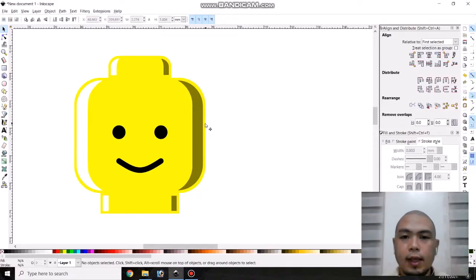Alright. So, yung kanina, when we started working, nung nag-draw tayo, sinabi ko early on na wala mo ng stroke yung shape, kasi yung stroke gives you a certain thickness or outline outside the shape. And it affects the dimension of the shape as you are working with it. So, very important kasi yung mga dimensions na yan, lalo na if, halimbawa, you are designing something for a laser cutting project, na importante yung tolerances natin. Yung dimension natin, eksakto. It's best to work with shapes na wala mo ng stroke. And then, kung gusto mo ng stroke, lalagyan mo siya sa bandang end part na pagpatapos ka na with manipulating the shapes, no?